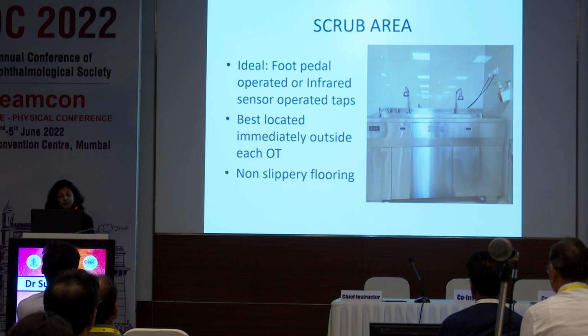Scrub area should be located immediately outside each theater. The flooring in this area should essentially be non-slippery, and taps should be either foot pedal operated or elbow operated or infrared sensor operated.